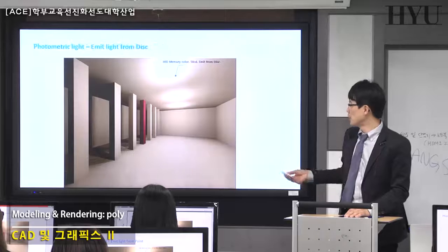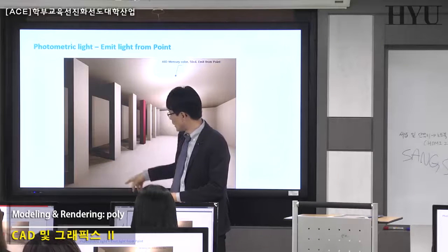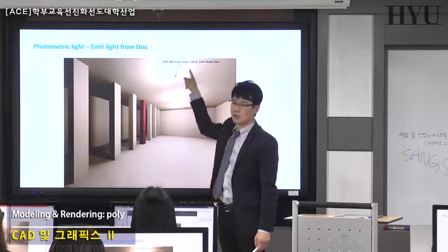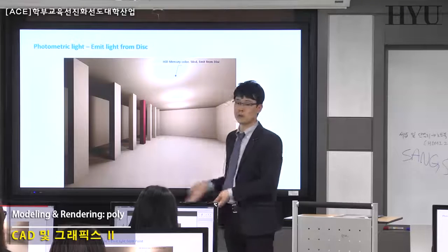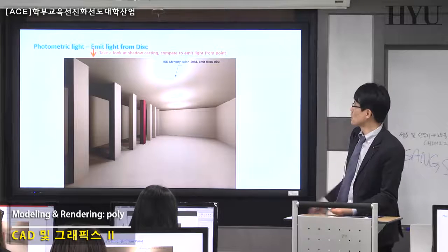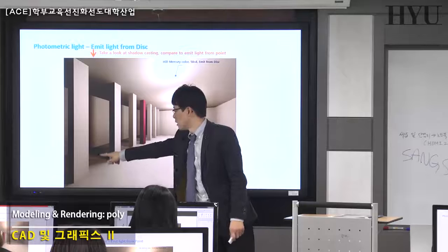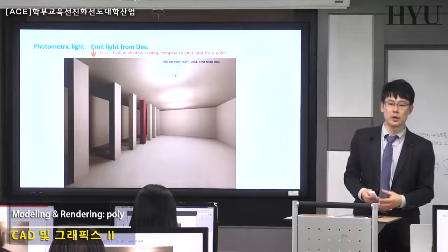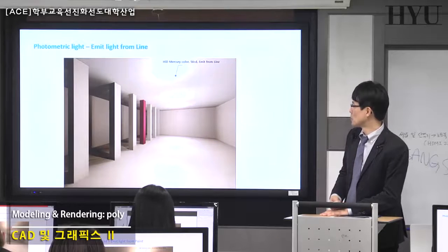But if you change, okay, take a look at the difference before and after. Simply because of changing the shape of that light from point to sphere, okay? Sphere light. Take a look at the shadow casting and compare before and after. Very smoothly shaded because of the shape of that light, okay? That's one way of controlling the style of light.